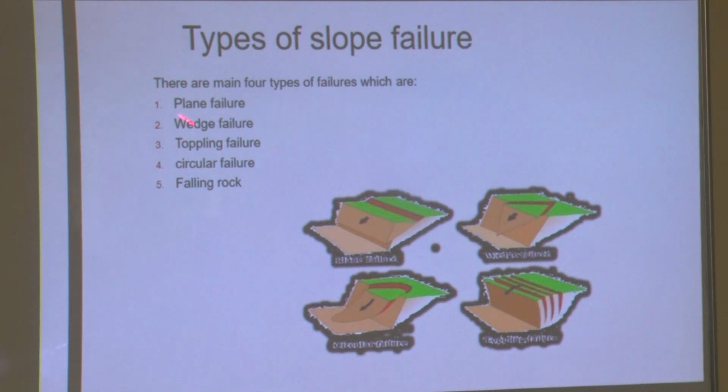In rock, the majority of the problem we are facing is with wedge failure, because you can understand when two joint sets intersect with each other, 2, 3, 4 intersect with each other, they will form a block. So that block is disturbed on all sides.